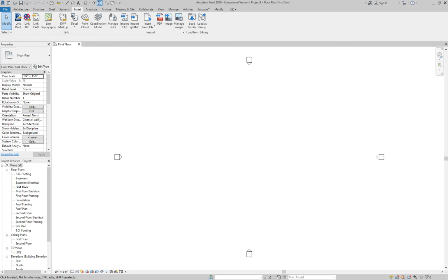So a lot of times my projects are, what are they called? Tenant finishes. So the structures are already there and the plans were done like 15, 25 years ago in AutoCAD. So I import them in, I mock them up in Revit, and I never look at the Cad plans again. So that's Import Cad. It's kind of a one and done.